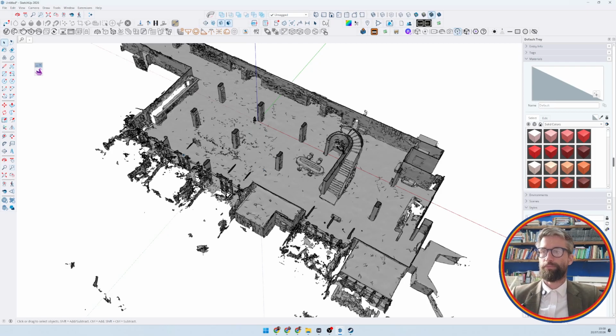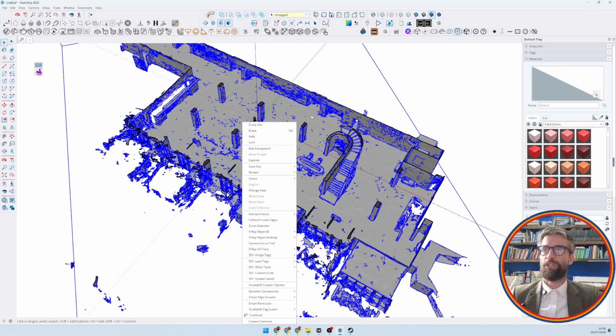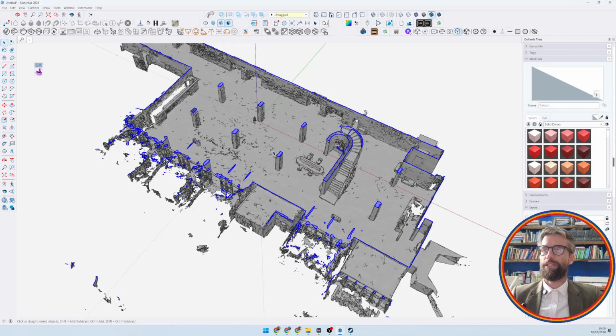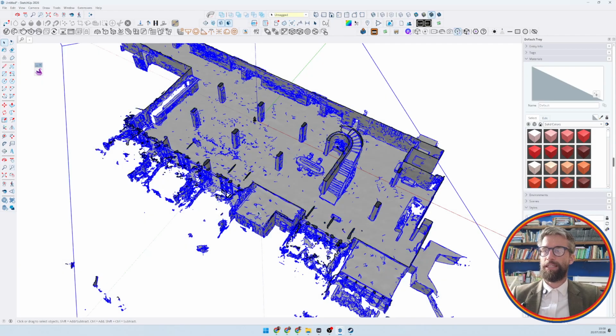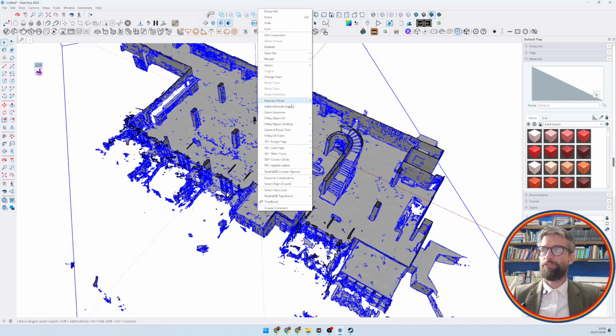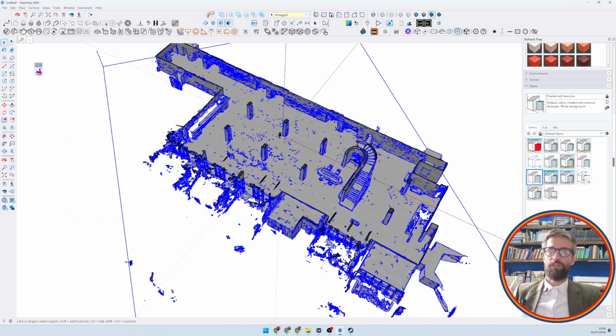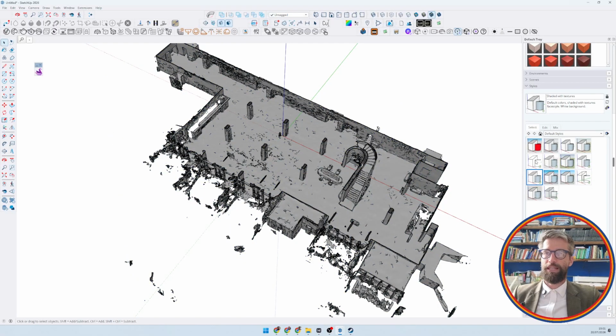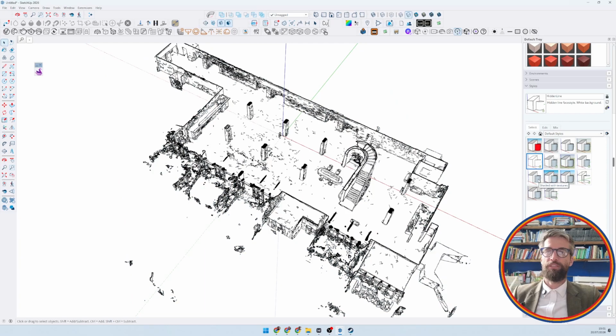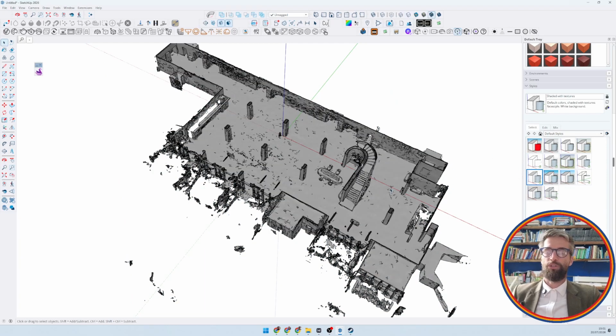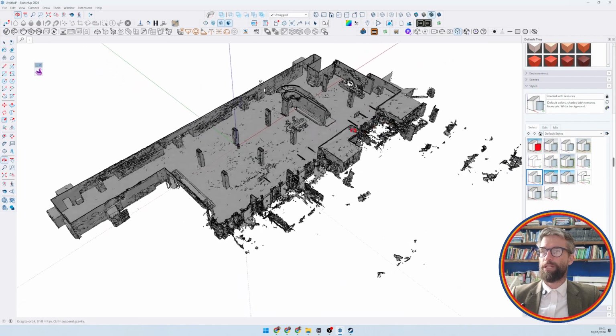single object. Then, as with so many other things imported into SketchUp in a non-native SketchUp format, the amount of triangulation that we then experience in an asset like this means that we can right-click and say Soften Smooth Edges, under which the Soften and Smooth Edges window opens, and then we can simply select Soften Coplanar. That way the object will appear slightly smoother. And we can switch between the different SketchUp styles to continue to use a fast style, so that a computer is not using too much of our memory banks to focus on rendering the actual object.